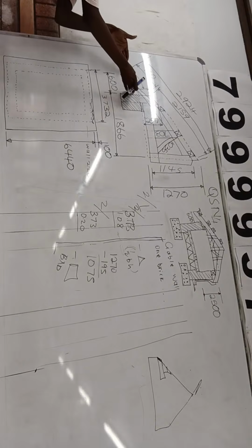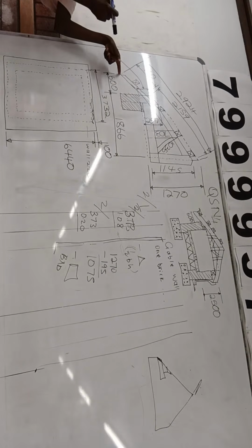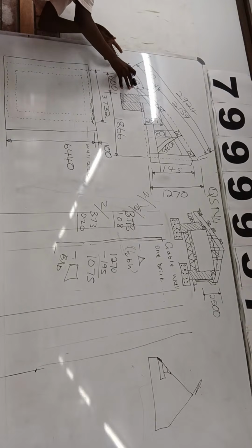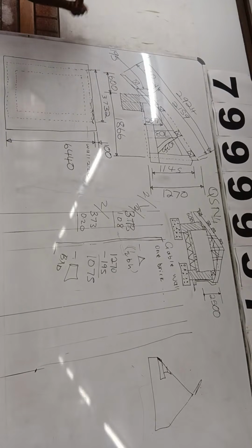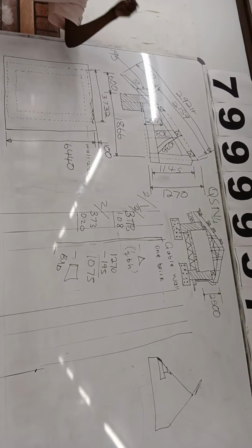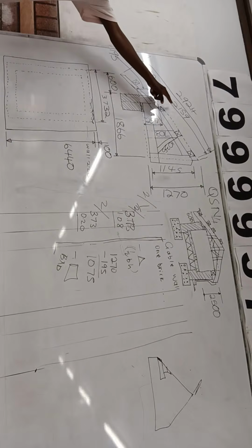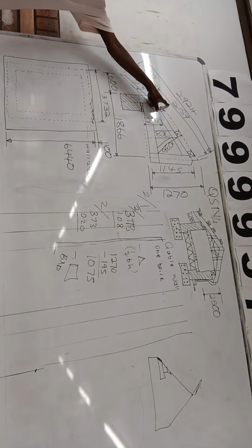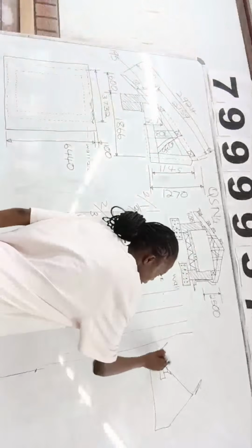This 2924 is where it is ending up. This empty space, there is no wall. Raking and cutting happens on the wall. It means where your wall ends, no more raking and cutting will happen. So that's how we know which one to choose between 2924 and 2159. So that's our height of raking and cutting. 2159.